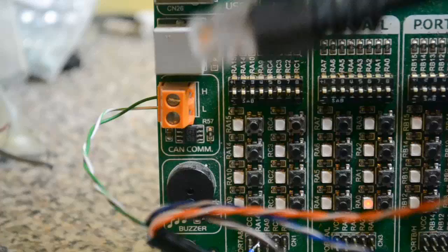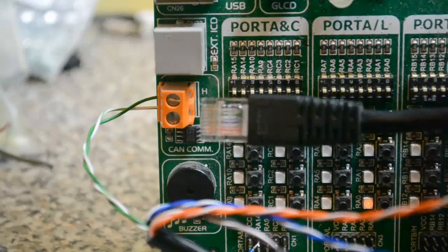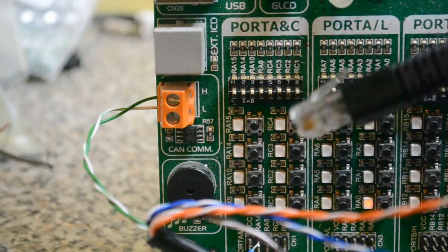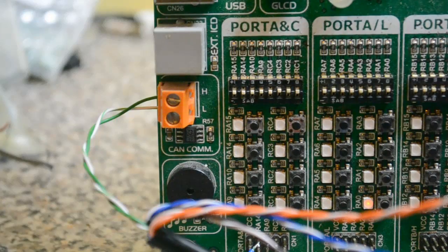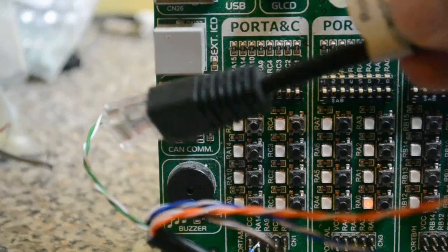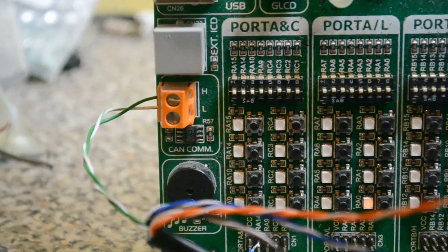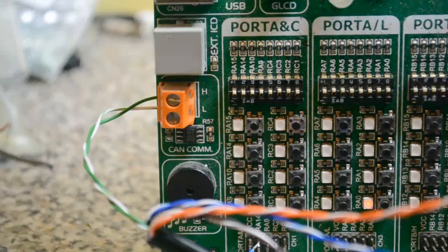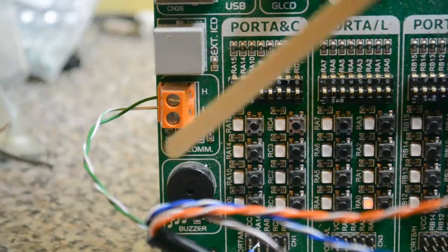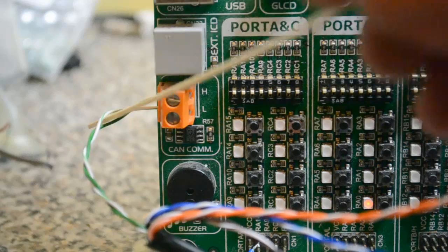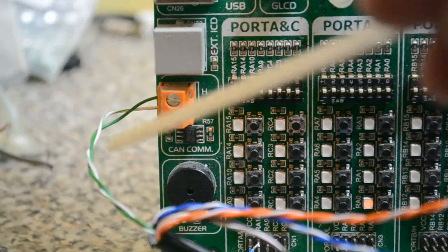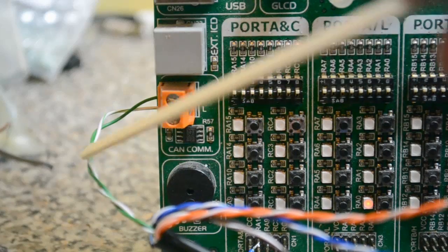So what I've done, cut up an old Ethernet cable. See, that's the old plug there. And you'll know inside, or you might know inside, there's 4 pairs of twisted wires. So CAN communication between one node and another, what they call the microcontroller's nodes, or the modules, between one node and another, you'll have a twisted pair. And here, to mimic Iveco's wiring, I've used CAN high is green and CAN low is white, although this has a green trace on it.